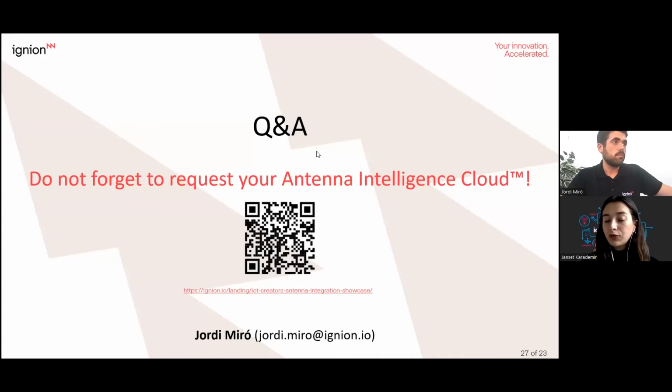Okay. So do you have any special consideration recommendations to improve performance for those small PCBs? Any special constraints with the virtual antenna? No, the ground plane layer is the main radiator of the system. So if you follow the design recommendations, for example, maintain the continuous ground plane layer. I think, for example, with the 20 millimeters by 30 millimeters, if you follow the recommendations in terms of ground plane layers included in the report, there are no design recommendations for further than this. Perfect. Thank you so much.